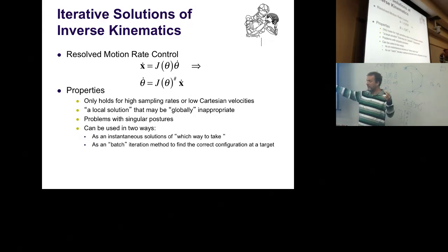Now I can do the same thing and give you a straight path in joint angle space. That would look like this. And you can actually see that I have this curved movement now in end effector space. Do we care? Well, depends. See, if you had the misery of life that this here is actually some narrow path where you have to go with a pen through, then that curved path will just run you into the obstacle. And the straight path won't. Other than that, if space is free, who cares? So this is essentially now up to you to figure out.